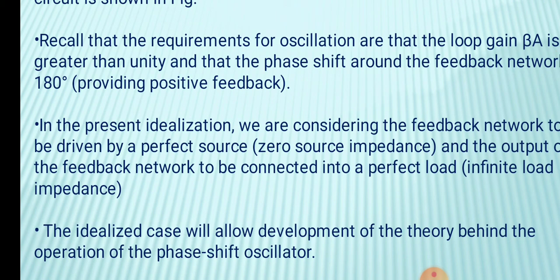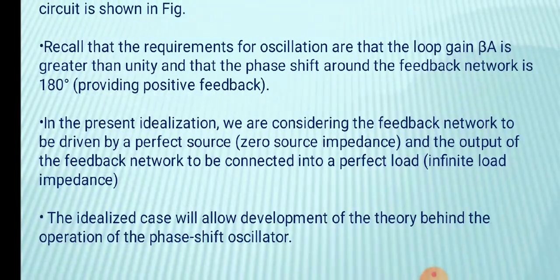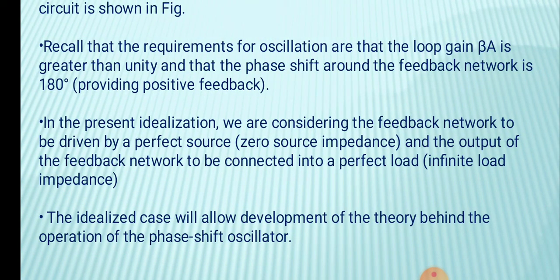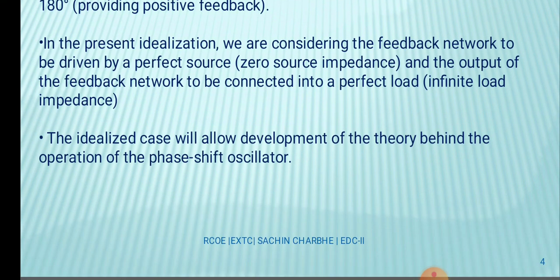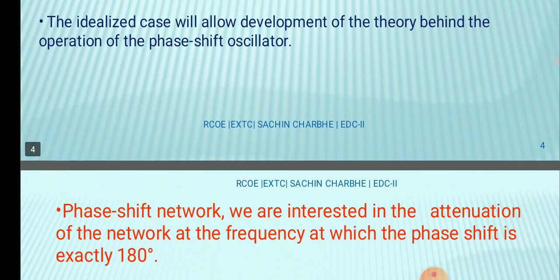In the present idealization, we are considering the feedback network to be driven by a perfect source, that is, zero source impedance, and the output of the feedback network is connected to a perfect load. A perfect load means infinite load impedance. The idealized case will allow the development of the theory and the operation of the phase shift oscillator.